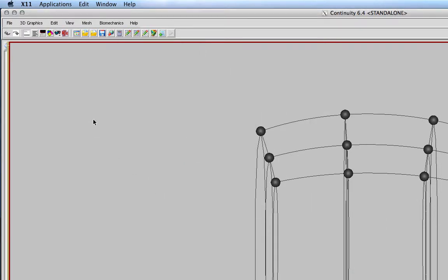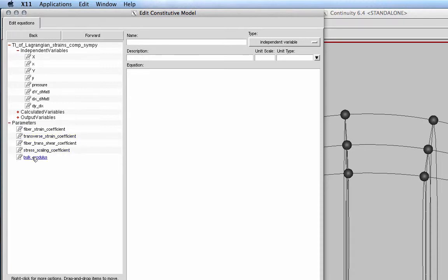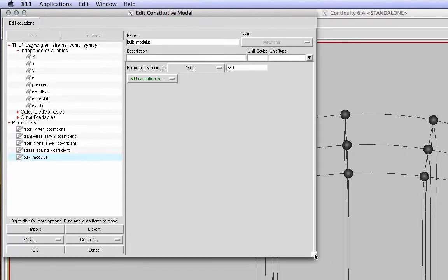The model has only 5 parameters instead of 8 for the orthotropic model. The last parameter is a bulk modulus of the slightly incompressible term in the model. It is relatively high and penalizes changes in volume as the tissue pressure rises. The higher this number, the less the volume of the tissue will change as the material deforms. A number that is too low can make the solution sensitive to the specific value. As the value gets higher, the solution changes less but can be harder to obtain.